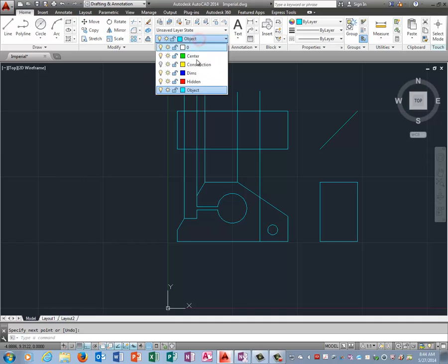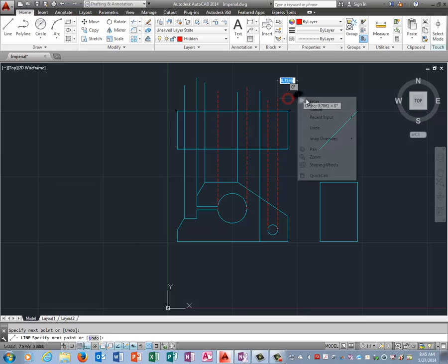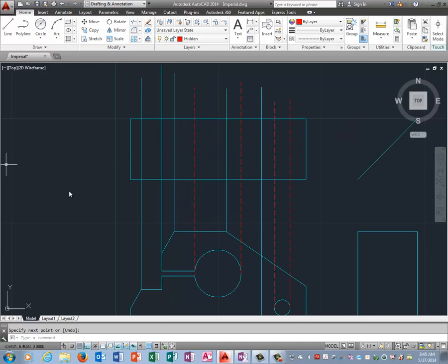So the next thing I'm going to do is project the hidden lines that make the circle. And then I'm going to do the same thing over here. Remember, diamonds are a girl's best friend when she's projecting circles in AutoCAD. So far, the top view is looking pretty good. I'm going to trim because all of these lines hanging out are going to make me crazy.